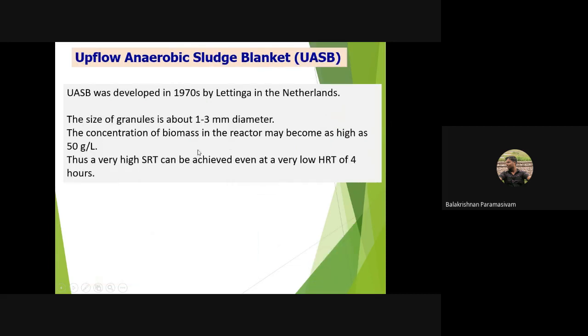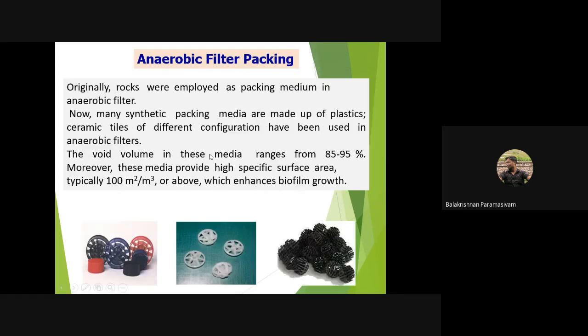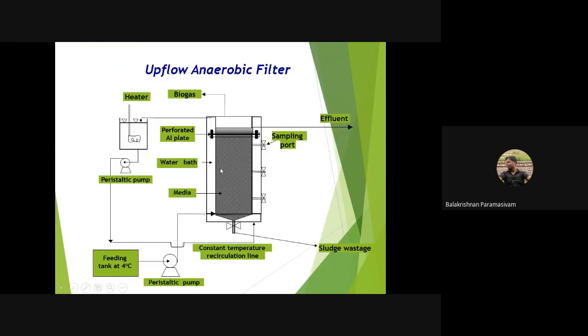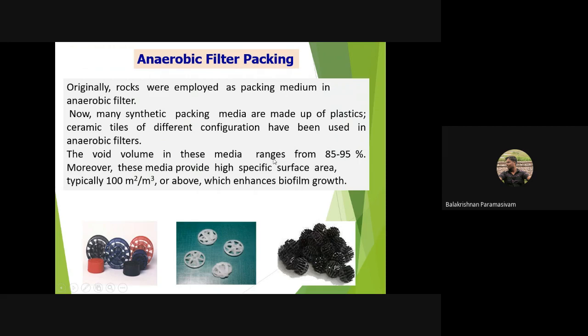Then upflow sludge blanket. Up to now, we are not at all using the anaerobic filter for real-time operation, because the filter media will get clogged, and maintenance is very difficult, because once we install, we have to lift the entire media for maintenance. So if it is clogged, taking all this media out is laborious work, and it is time consuming.